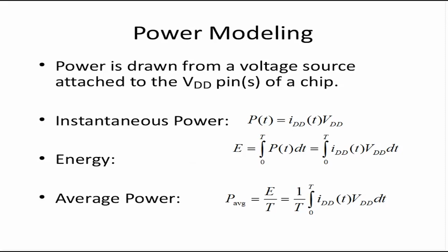This is the reason that now, as the technology shrinks, as we move on to the nanometer scale, the deep submicron, the VDD is reducing. So earlier, in 90 nanometer, 130 or 180 nanometer, the VDD went up to 1.2, 1.5 volt. But now we are in the range of 1 volt, 0.9 volt. So as we decrease VDD, obviously the power is decreasing. For example, handheld applications like mobile phones, hardly any chip will require more than 1 volt for the digital portion, right?